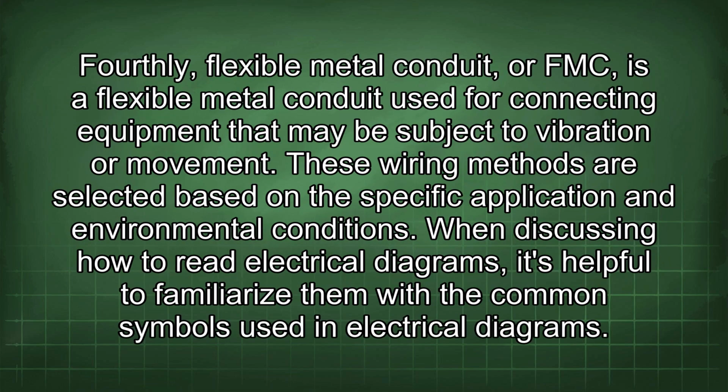Fourthly, flexible metal conduit, or FMC, is a flexible metal conduit used for connecting equipment that may be subject to vibration or movement. These wiring methods are selected based on the specific application and environmental conditions. When discussing how to read electrical diagrams, it's helpful to familiarize students with the common symbols used in electrical diagrams.